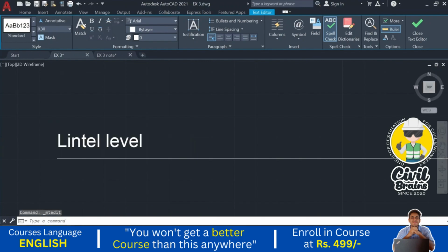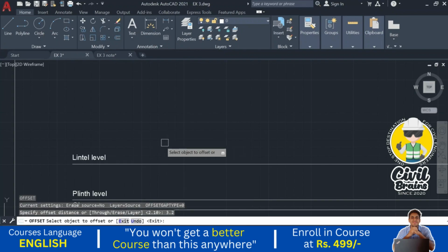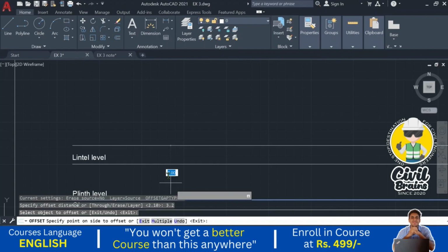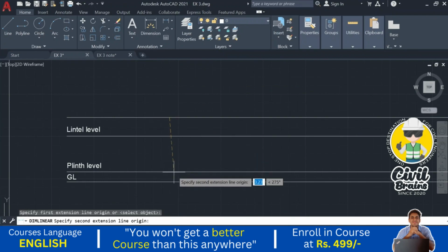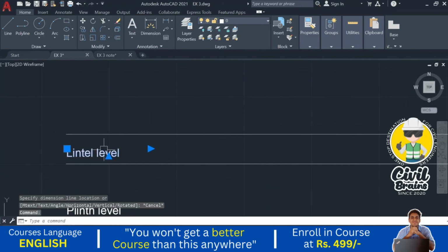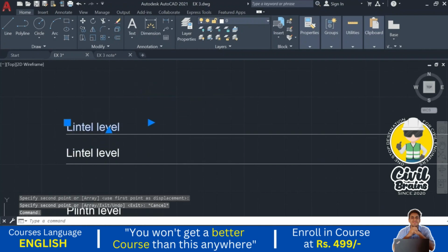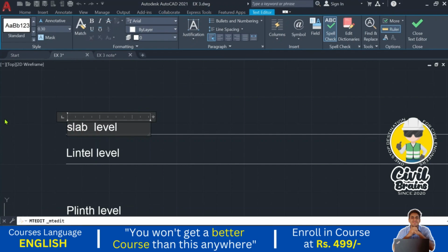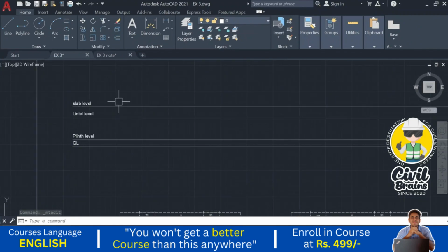Lintel level. Okay, next roof slab height, that is also the bottom of the slab, floor to the bottom of the slab. Offset, that is 3.2 meter, correct? So from the floor level, this is our floor level, 3.2 meter. I just check whether it is 3.2. Yes, 3.2 level. I just copy this one, slab level. Okay, so what is the next step? So we have drawn all the levels.